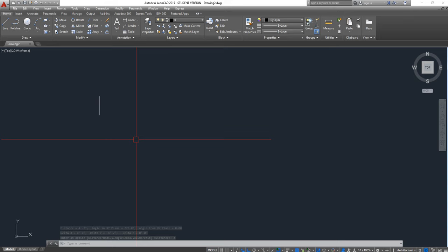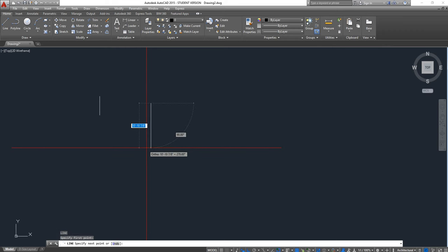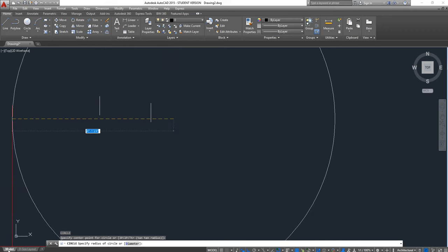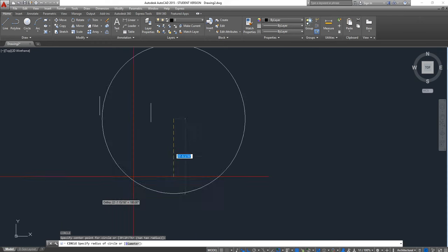This is how to create a line. I either click on a line, or I can enter the command L, enter, 4 feet 7, enter, escape, and here's my 4 feet 7 inches line. Also the circle, I can click C, enter, click in the model space. This is model space. We have two spaces, model space and layout space where we print from.